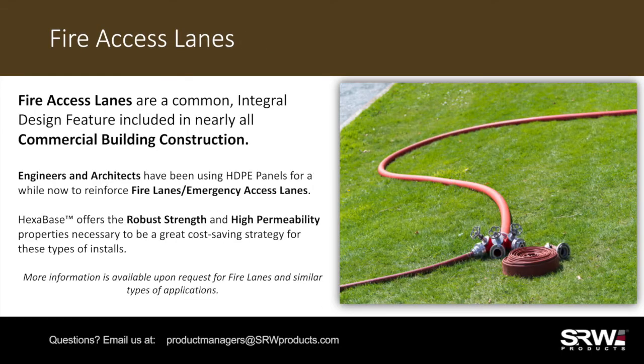Over the last several decades, fire access lanes have become a common integral design feature included in nearly all commercial building construction. These fire access lanes are areas of reinforced soil, typically using a traditional aggregate base where heavy loads can be driven next to a building to offer fire and emergency services. Recently, engineers and architects have been using HDPE panels to reinforce these fire lanes and emergency access lanes. HexaBase offers the robust strength and high permeability properties necessary to be a great cost-saving strategy for these types of installs. Typically, the construction details of fire lanes and emergency access lanes are designed by an engineer and can vary greatly from project to project. More information is available upon request for fire lane installs and similar types of applications.